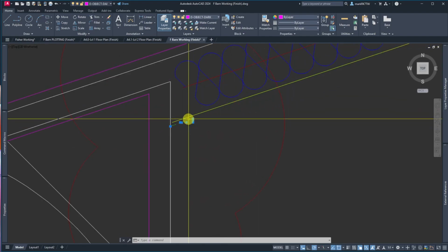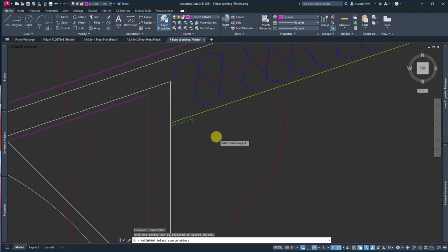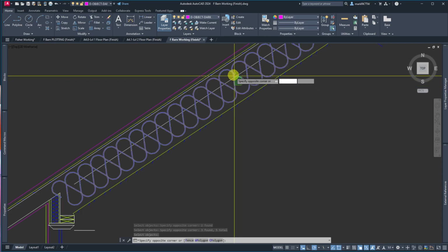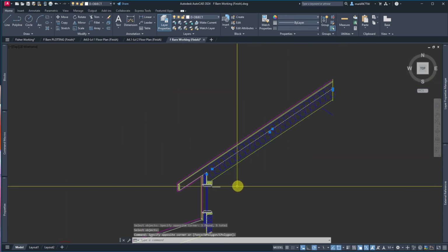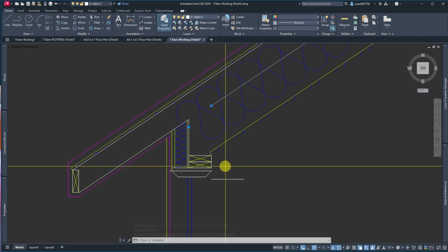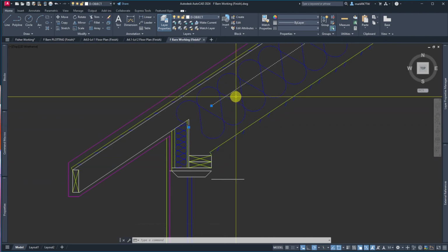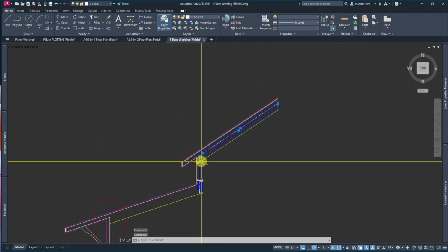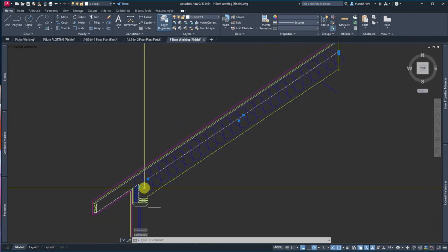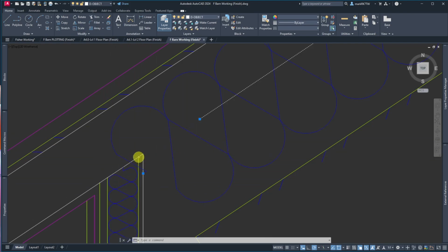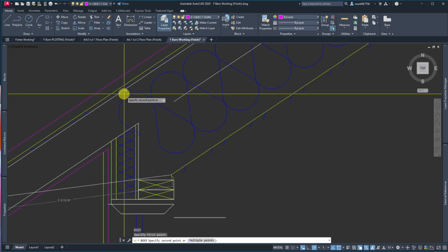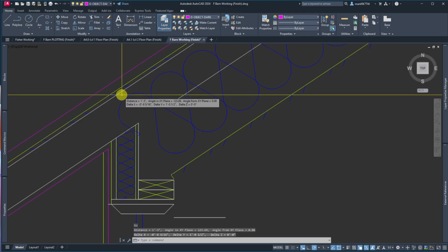Don't think I need any of this. I certainly don't need insulation. That all can be reserved for the section. And then I'll get rid of the insulation here as well. I don't want to get rid of that line yet. I've got sheathing. I've got a 2x. Yeah, no, this can go away. In fact, I don't even know that should be there. I think it was used to make this extension out. But this should be a 2x14 to get that depth. So if I go distance from here to perpendicular to there, it should be 13 and 3.